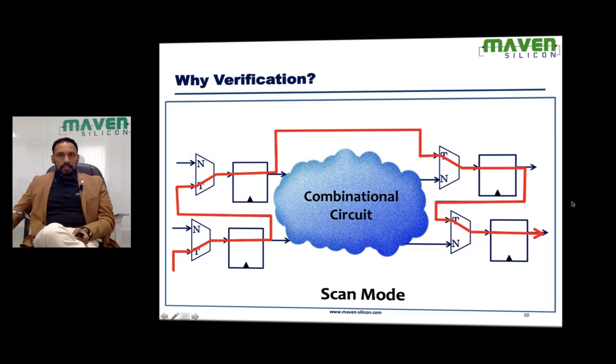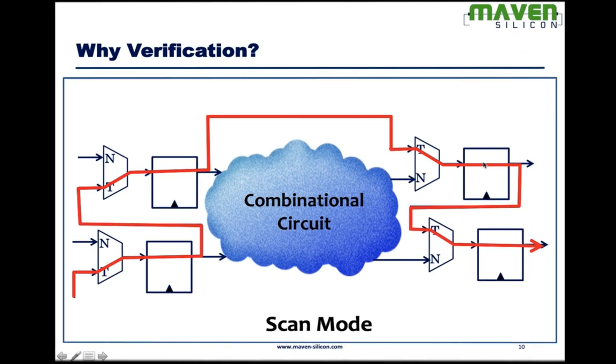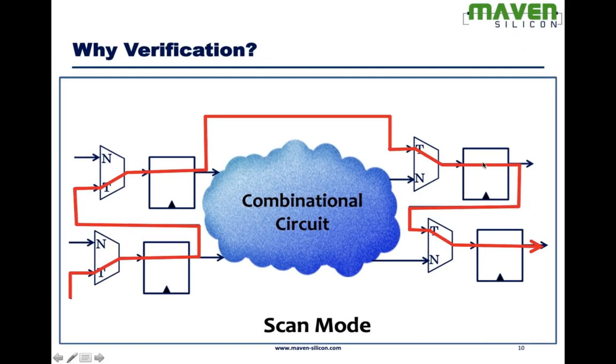We inject the stream of bits through this flip-flop, and all the bits will flow through all the flip-flops, and eventually we should get the same stream of bits at the output flip-flop. If it works fine, then we can confirm all the flip-flops work fine. So this will be useful to identify the fabrication faults later.